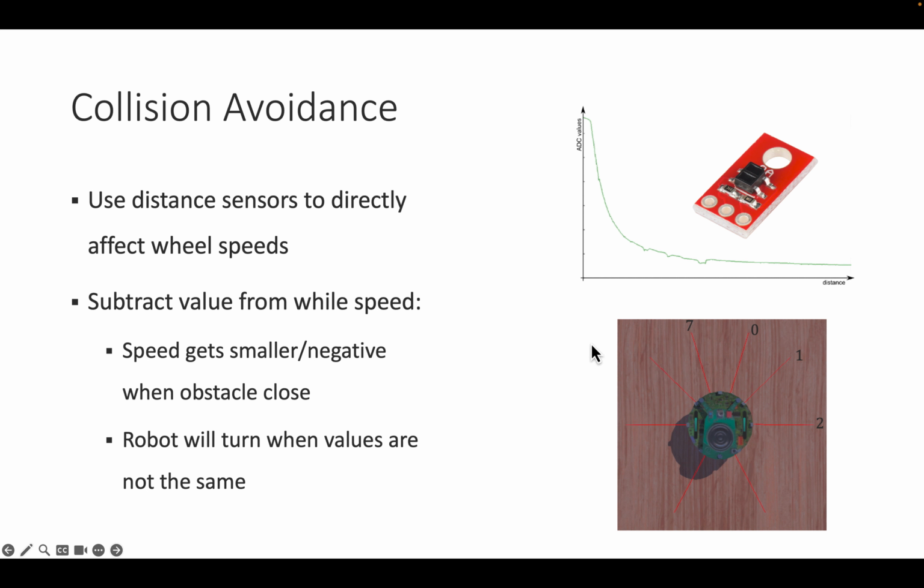You can also use this to avoid collisions, and you've seen it in the video. The shell has been connected to a sensor that, when triggered, let the robot move in a random motion. You can do better than this with more directed sensors, like on the ePuck, and we talked about the proximity sensing in the last module.